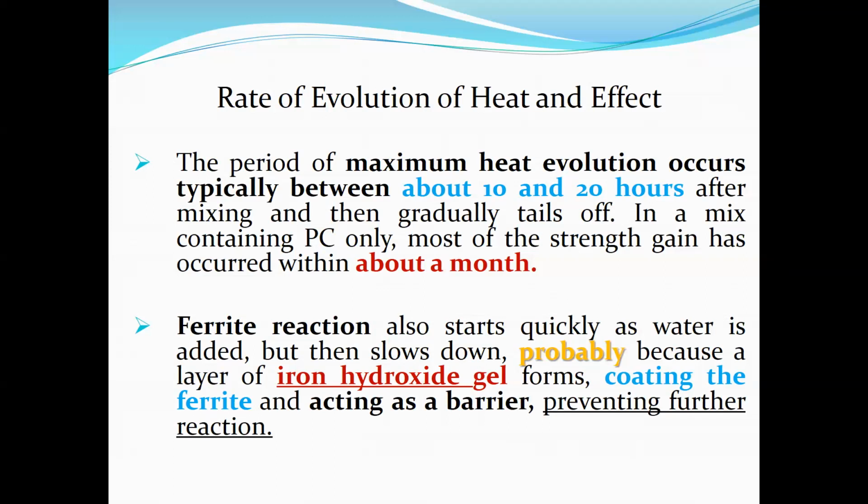But it slows down probably because a layer of iron hydroxide gel forms, coating the ferrite, and it acts as a barrier. So ultimately further reaction doesn't take place.